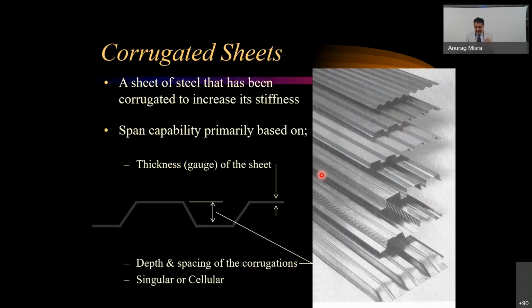So these are other types of corrugated sheet. As I mentioned just now, these are the conventional corrugated sheets you see. Nowadays, there are different types of sheeting materials. Some of them are simply GI, and the others are zinc and aluminum, galvalume, and these days you could also see colored sheeting. Some of the companies have patented their coating technology, and these days it is becoming very popular across India.